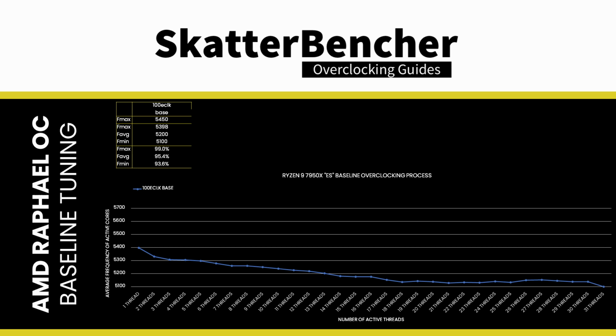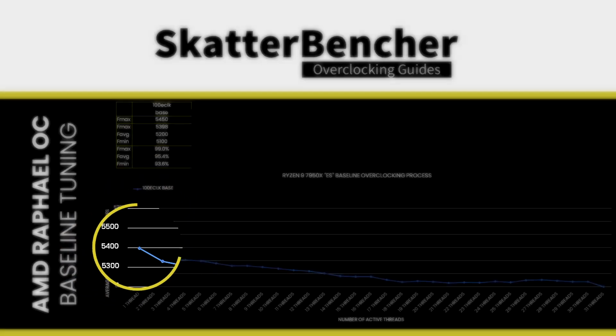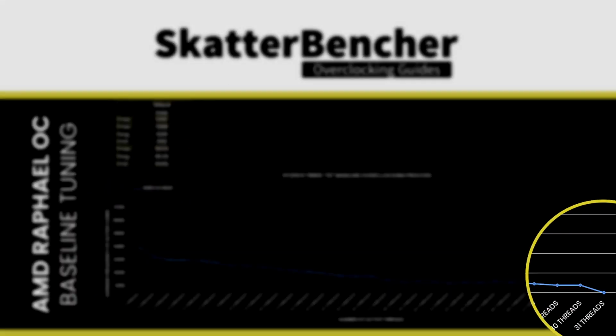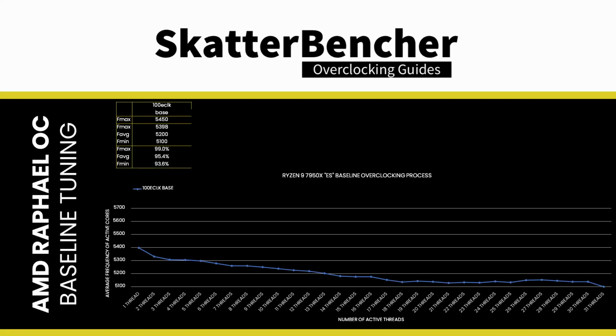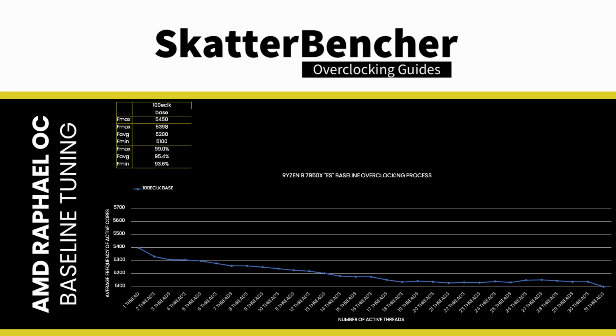The baseline frequency is characterized by this line and ranges from 5398 MHz at one active thread to 5100 MHz with 31 active threads. The programmed Fmax is 5450 MHz, meaning the base configuration effective Fmax is 99% of the programmed Fmax. This will be important later on. The average frequency is 5200 MHz and the minimum frequency is 5100 MHz.